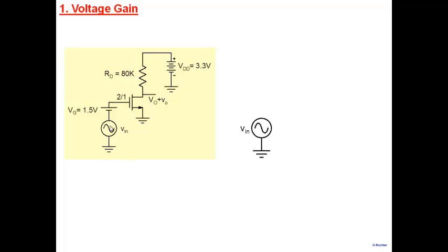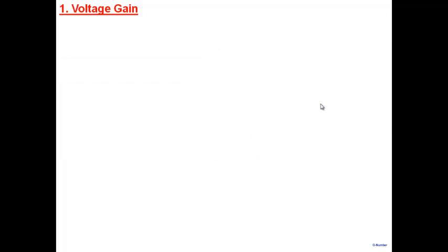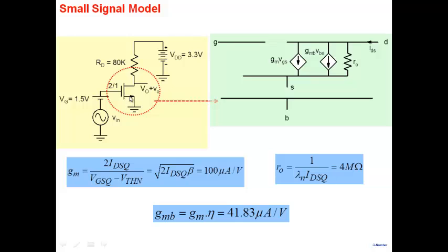As usual, I'm doing it gradually. So this one is going to short out. We'll replace the transistor by its small signal model here. Now go back and see in this particular model that the body is connected to the most negative point in the circuit, and the most negative point in the circuit here is the ground. So the body is connected to ground and the source is also connected to ground. So this VBS will not be there, which means that the body to source voltage is 0, a constant, and therefore the small signal body to source voltage is 0 here.